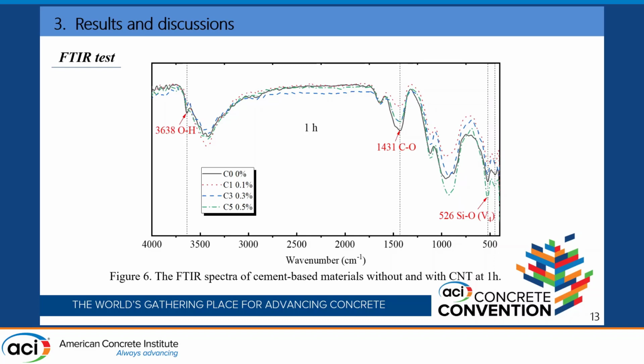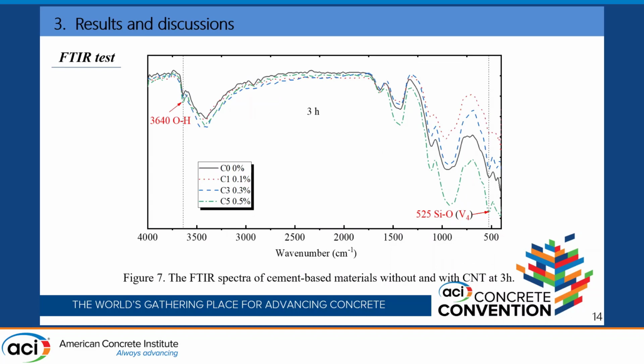And I think the main conclusion, even with different hours, is there are no new peaks. So there are no new hydration products. But you will see an increase in the peak corresponding to OH. One thing I wanted to point out, which I showed before, is that the frequency at around 500 increases with the addition of CNT. And that means that there is more polymerization when we have CNT as far as the tetrahedron is concerned.